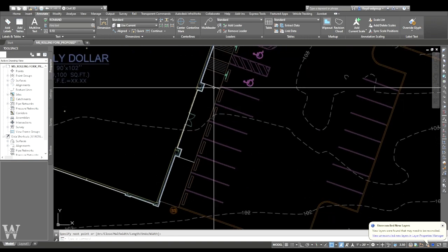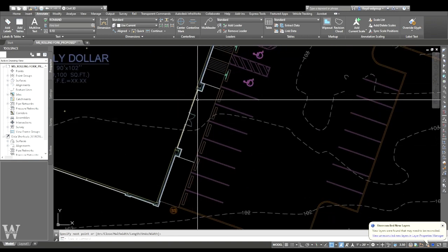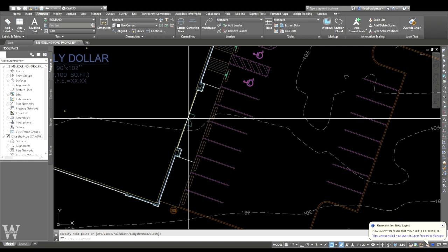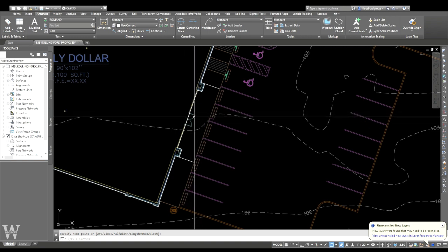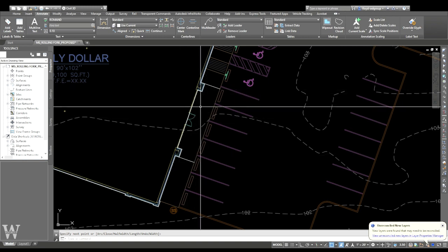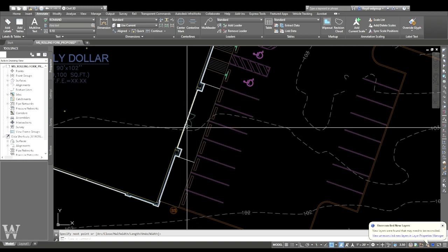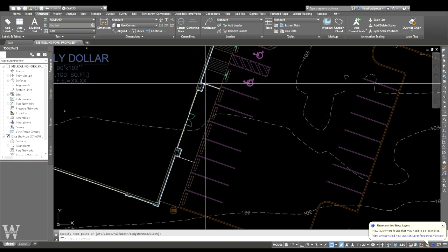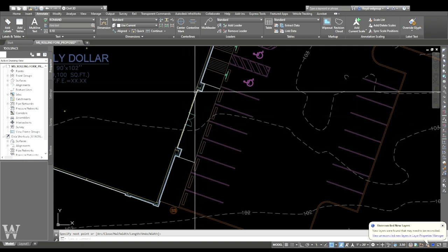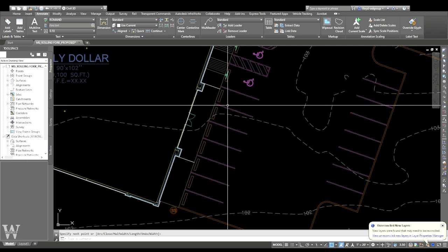So when I grade this area, the front door can only be a 1/2 inch difference in the sidewalk right here for ADA access. So what I do is I make this whole front part from this point to this point the same elevation, actually all the way to, and then I slope away from the building at 1%.